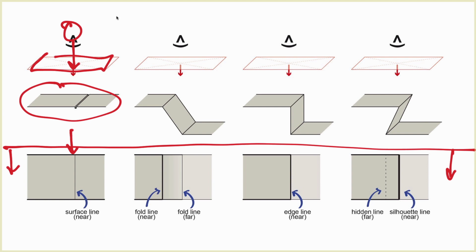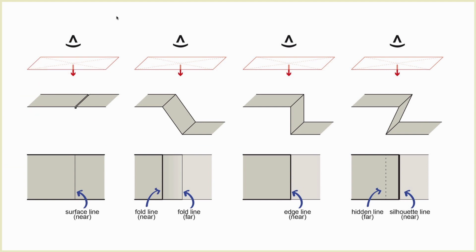As we look at the next one, drawing 2 here, this slopes down and away from us. So the boldest line is right there at the topmost edge. Then we have a thinner line right there and right there. And then we have the thinnest line of all here and here. So the further away we go, the thinner the lines become. So things that are closest to us have the thickest lines, and things that are further away have thinner lines.